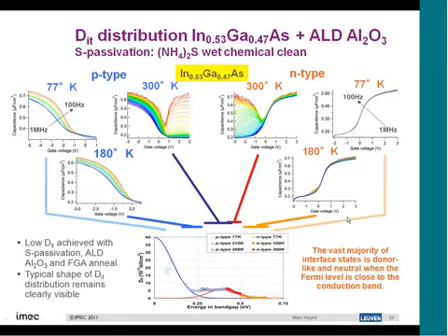First of all, I want to point out that over the years we've been spending quite a lot of time learning how to analyze these surfaces, because many people came from the world of the silicon business, and they were using the typical ways of measuring interface states and defects on silicon, and just transferred that to the III-V materials, forgetting that you work here with materials that have a different band gap, different time constants for charging and discharging of the traps, and different minority carrier generation times.